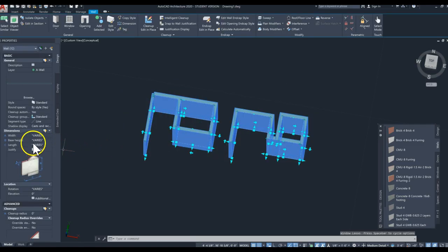And now let's go change the height of all of those walls at once. Notice how they're not the same. So I do 9 apostrophe and then I click enter with my keyboard. Now they are all 9 feet. To deselect, click escape on your keyboard.